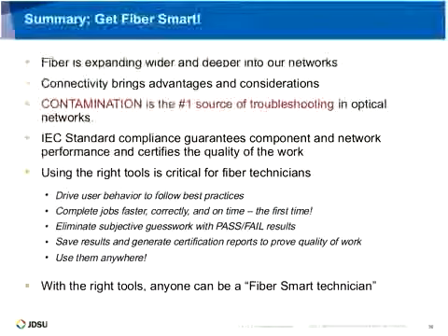So if you had clean fibers before they made physical contact, nothing's going to get in there, with the exception of, let's say, the occasional outside plant situation where a connector is in a box at ground level or underground, and there may be water that gets in there. So things like that potentially run the risk of creeping in.